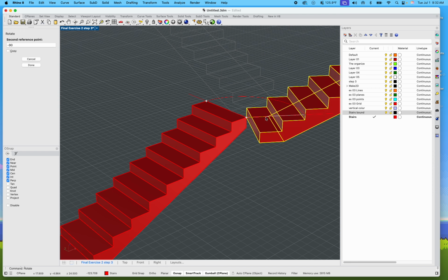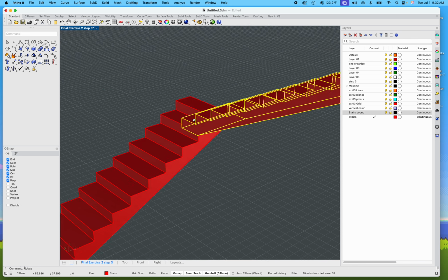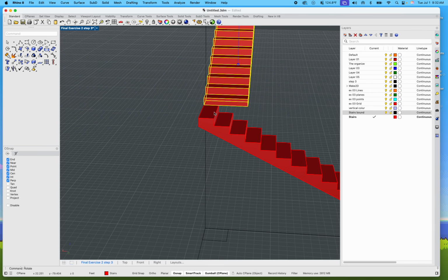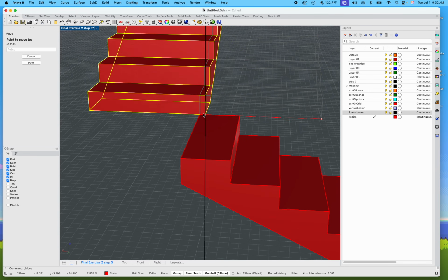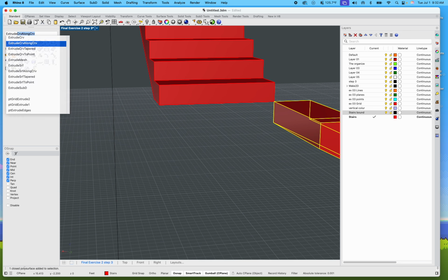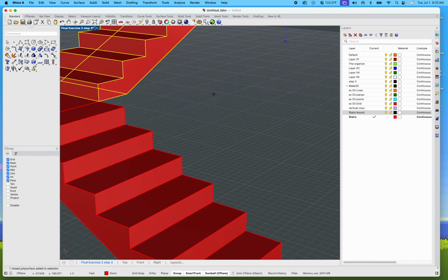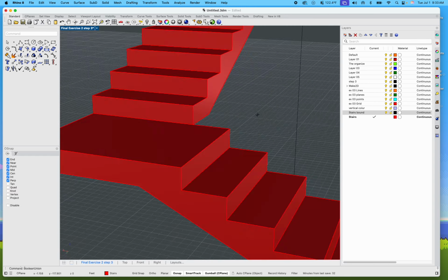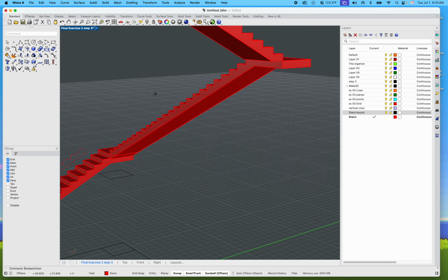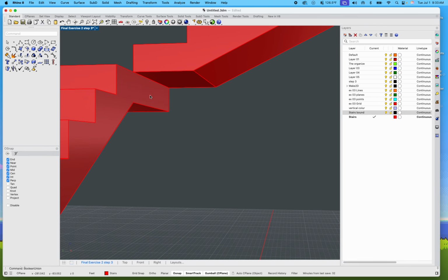Take a known, right? You guys may notice that I'm only taking certain spots that I know are going to kind of continue that 90-degree angle, and really using the object itself to really govern where I put it. So again, taking certain pieces to make sure they line up. And that's a pretty easy fix, right? Obviously just extrude, surface, enter, take that one, and go across. Same kind of things. Again, I can put those together, Boolean union, and nobody would have to know, right? Probably did that a little wrong, but I kind of want to show you different things and different methods anyway. So that one's looking a little more of alignment.